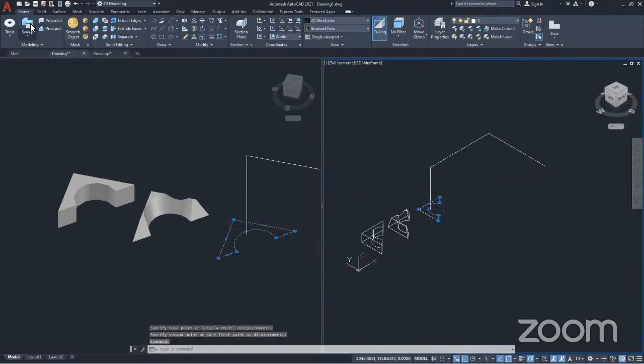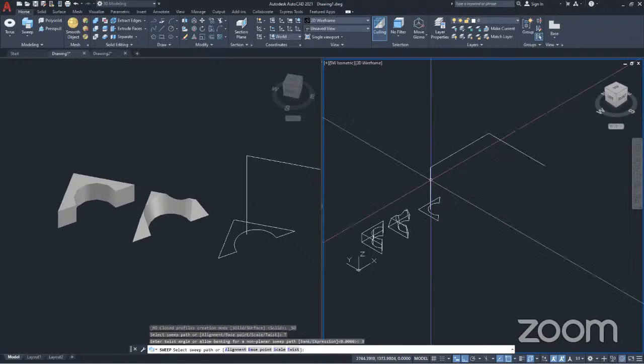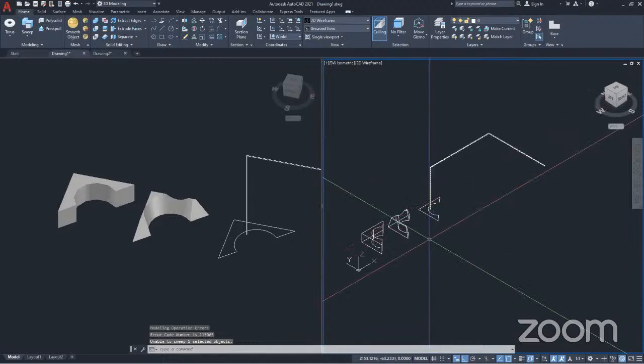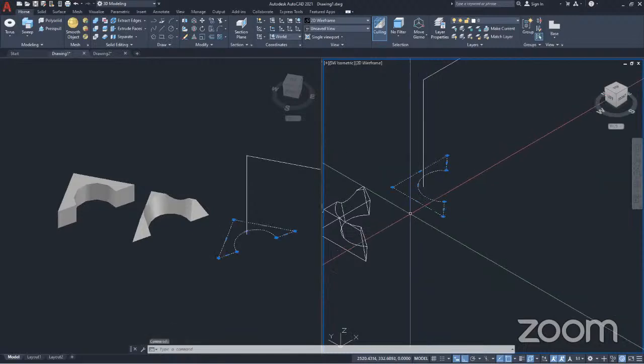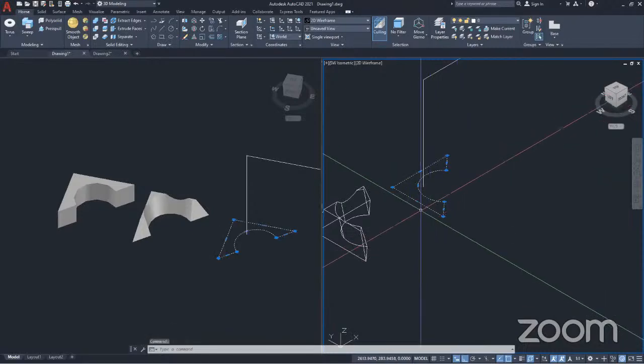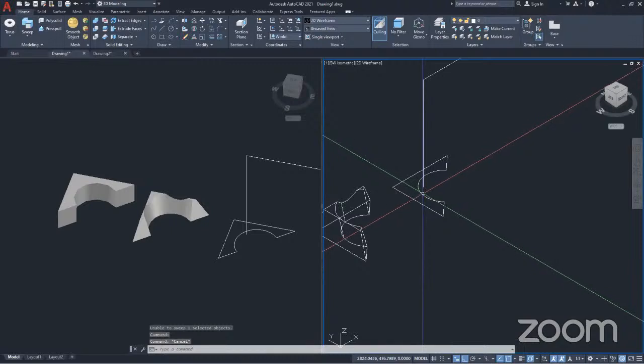And let's repeat again. Sweep. Twist. 3 degrees. Twist angle around back. Okay. Now path. Let's see this path. If it will work. It's not working. I think this is just too big for that angle of twist. So we look for something like a simple polygon, something smaller. Let's see if I can resize this.